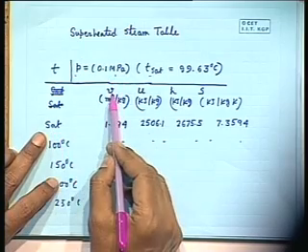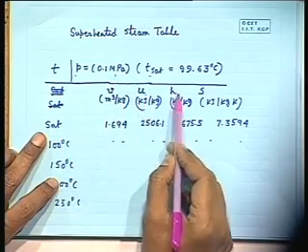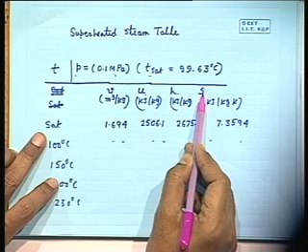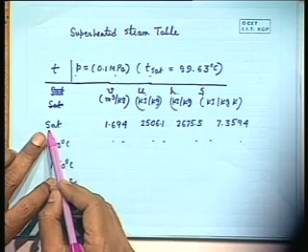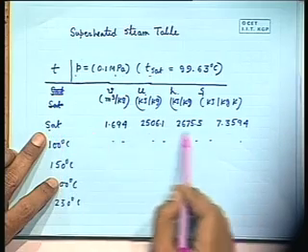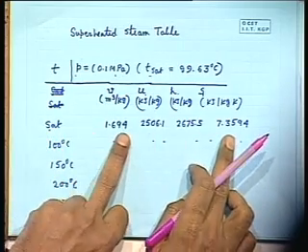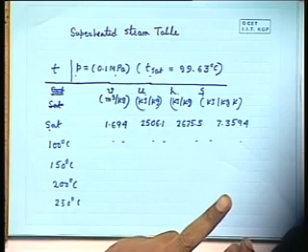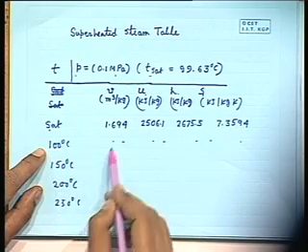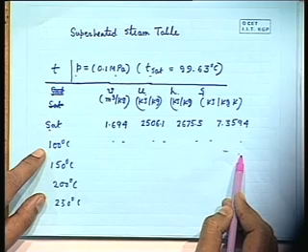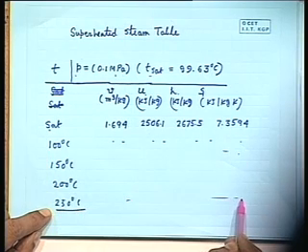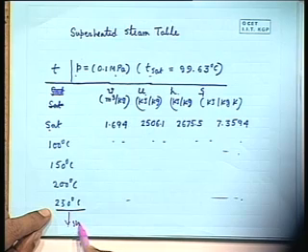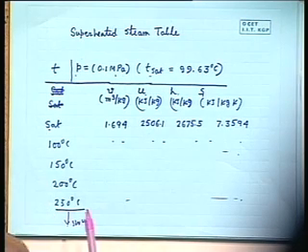Then it tabulates the specific volume, internal energy, enthalpy and entropy of the superheated vapor at that state. First they tabulate the saturated state. These are the saturated state values, which coincide with the values for the dry vapor in the saturated steam table. Then they tabulate with different temperatures. That means if you want to find the properties of superheated steam at 250 degrees Celsius, you see this, and go on to 500 degrees Celsius and so on, up to a certain limit. That limit depends upon our usable working range. Clear? Okay.